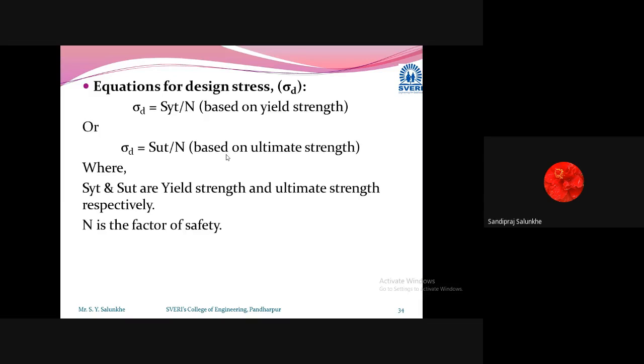Then he considered that at a time 120 kg multiplied by 4 people, they are standing continuously on that footrest. It will become 480 kg. And then he used factor of safety as a 2. And it becomes 960 kg at a time. And that part was sustaining in the market.